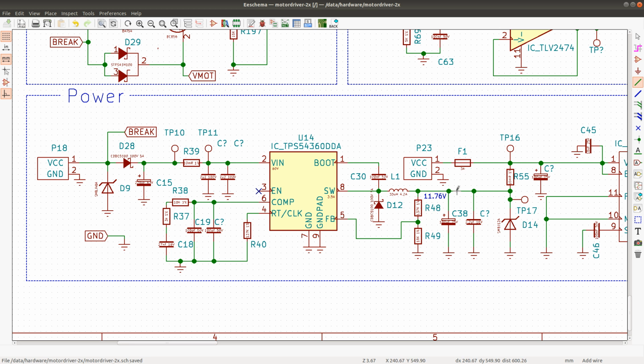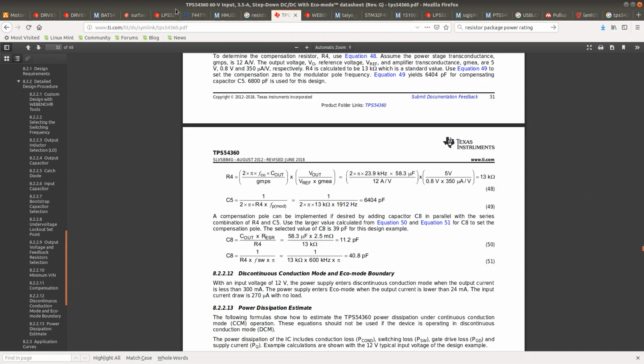What I need to do here is make sure that we have a fuse right here, so that if the voltage rises beyond something like 14 volts, when this diode starts to conduct, this fuse will go. And this fuse does not need to be any large fuse. It can be a small SMD fuse, because under normal circumstances it will never fire. And we can set the fuse value at 4 amps.